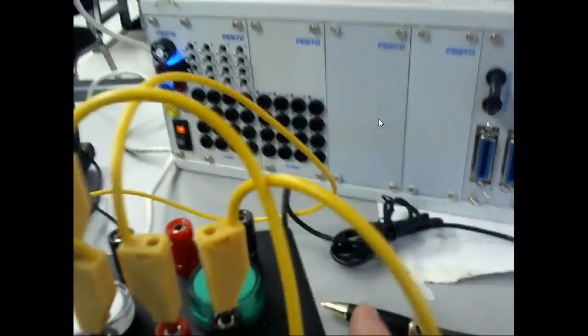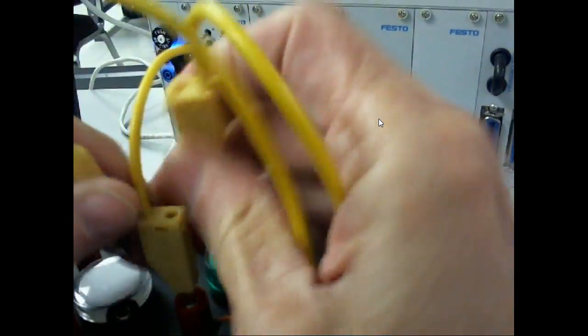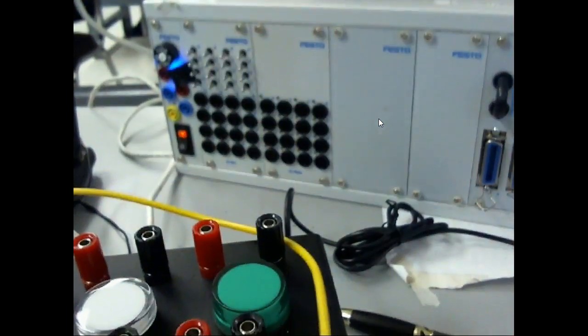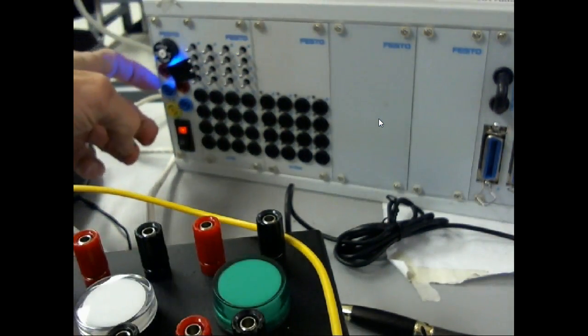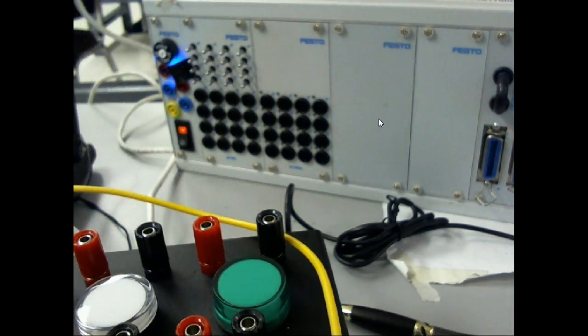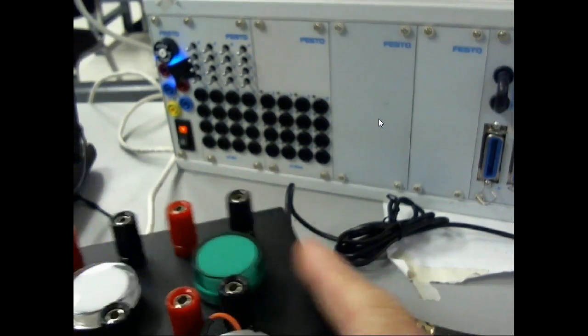And what I'll do now, because y'all know the motors are going to run, right? So all my output devices, if my outputs are set up to source, I would just take that negative and just jump it to every one of my output devices, right? As my common, right? A negative common.